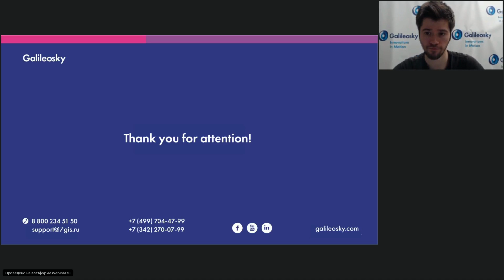So always use a delay element when creating cycles. You can set any delay, it may be less than a second, it may be 100 milliseconds, but it is recommended to have one.